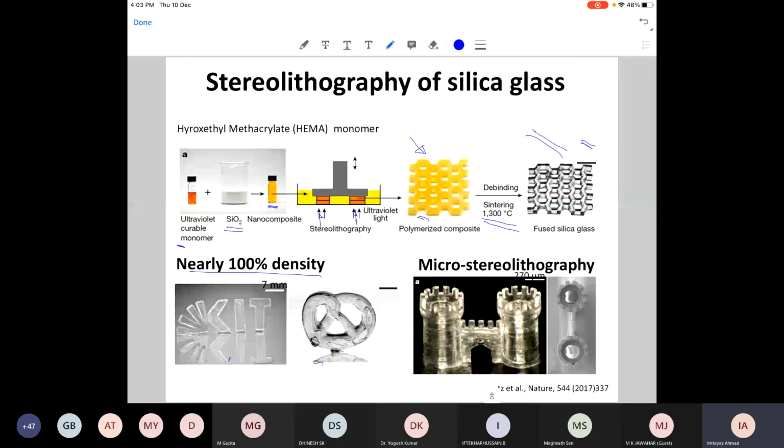And when you inscribe the structure, these photo initiators and the monomer will connect together and give you a three-dimensional network, which can withstand on its own. It's kind of a polymer. Now, this is called a pre-ceramic polymer, which contains a lot of silicon oxide, silicon carbide, and silicon nitride. You can go by the mixture of it. You will produce silicon oxynitrocarbide, or if you take only two, you get silicon oxynitride.